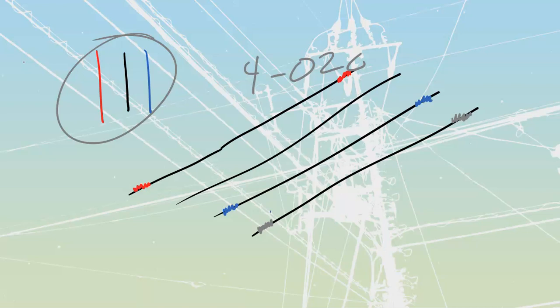And the very last section inside of this learning task talks about a concept that we've talked about a ton, which is our high delta. We've talked about this a number of times, 4-wire delta, where we have that one center tapped winding that's between the B and C. The high leg has to be A. The panel board has to keep A away from the B and C so that we don't accidentally stick a high value of voltage across to our neutral. And we have to just keep that high leg separated across these. But we've gone over that so many times at this point, I'm going to skip over that because you should be fully fluent with these concepts.